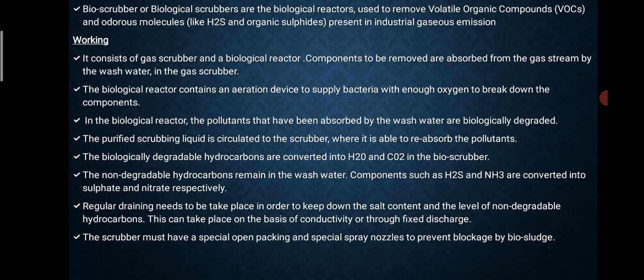The biologically degraded hydrocarbons are converted into H2O and CO2 in the bioscrubbers. The non-degradable hydrocarbons remain in the wash water. Components such as H2S and NH3 are converted into sulfate and nitrate respectively.